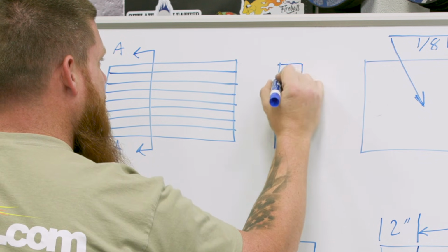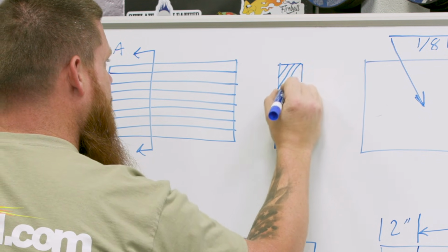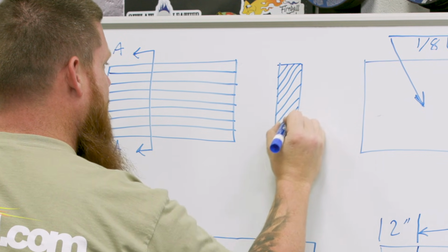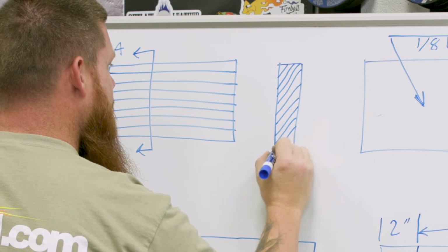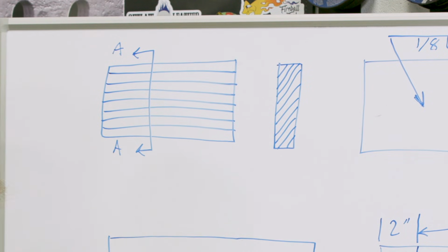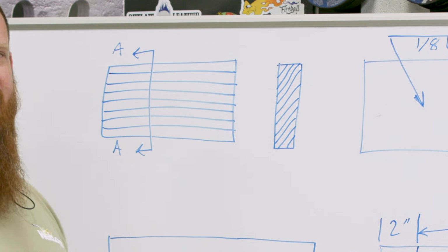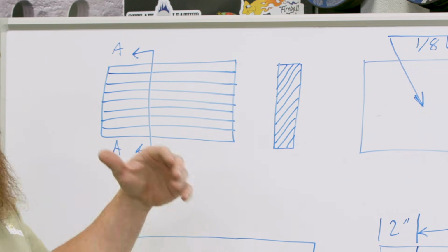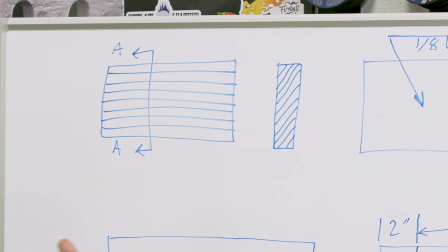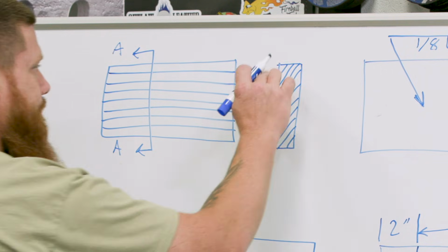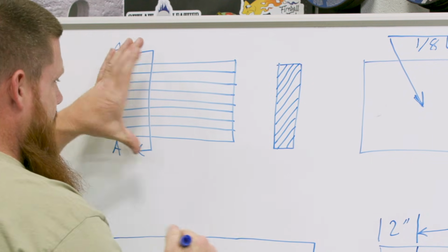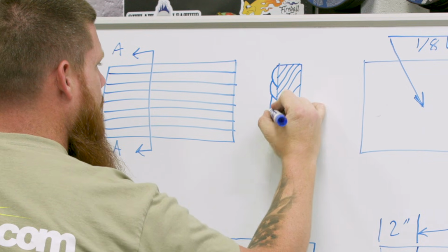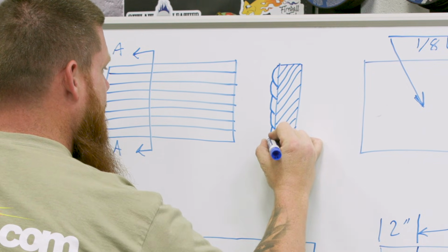Okay, and I would know that because there would be another drawing next to it that's going to have that rectangle shape with hatching in here. And due to ANSI standards, each type of material is going to have a different type of hatching. So concrete has one different type of hatching. Aluminum, steel, everything's going to have a different pattern of hatching. But what this is essentially going to show me is all my overlapping welds. So that's how they would lay in there, just like that.